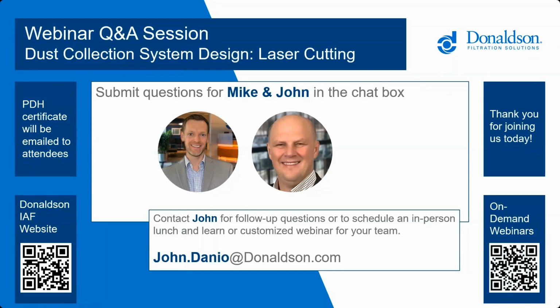Usually we recommend that once you get to 4, you either want to clean, or if you continue to clean and you can't get below a 4 on the sag pressure, then it's time to change the filters. So there's a couple different ways to gauge that. Most of our systems will have an ability to look at the sag pressure, and when you get over that level of 4 is when you have to start looking at cleaning or changing out those filters.